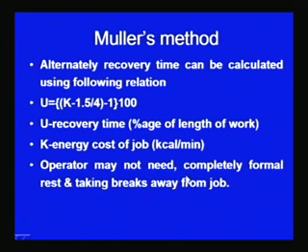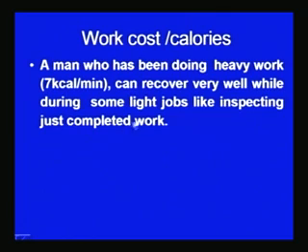The operator may not need complete rest. He may be given some other job which consumes a lesser amount of energy. The operator may not be required to go completely off the work, but he may be asked to do certain other things which consume less energy. For example, a person who has been doing heavy work and consuming energy at the rate of 7 kilocalorie per minute can recover very well while doing some other light jobs.